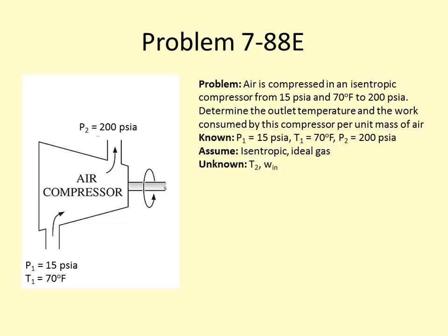If it were an actual compressor, would our work input be greater than or less than this number? Greater than. We'd have to put more work into the system because there would be irreversibilities that we had to overcome and likely heat losses.